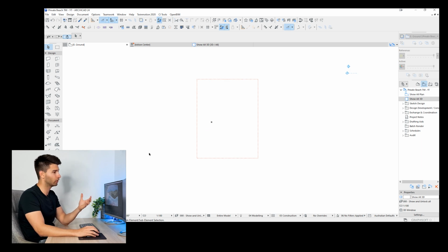Depending on the hemisphere you're designing in, you may either want to locate all of your living rooms to the north or all of your living rooms to the south. In this instance, we want to locate them all on the north side and have our sleeping in the south side. At the same time, we don't want to be missing out on this spectacular view. So what I'm going to actually try and accomplish with this is to recess the bedrooms as far south as possible without actually losing that northern elevation.